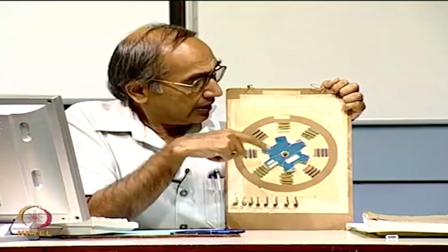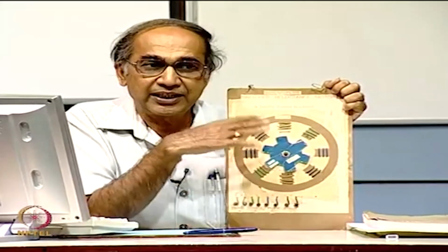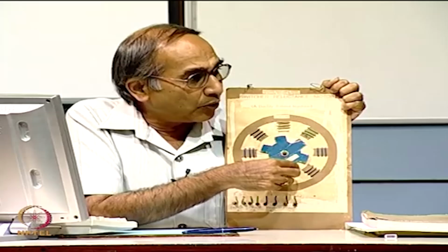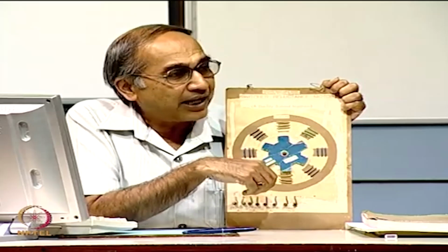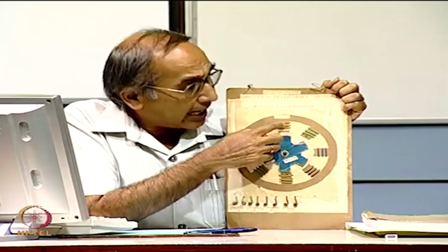One thing you know is that the inductance of these coils is not constant. Is the inductance of each coil constant? Why is it not constant? Variable air gap, because for different rotor position it will have different inductance. For example, at this point this yellow coil will have maximum inductance because its rotor is aligned.